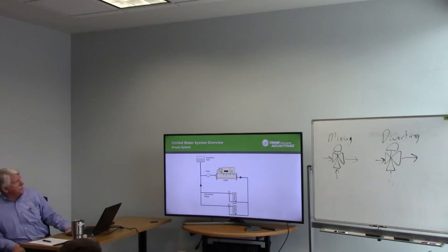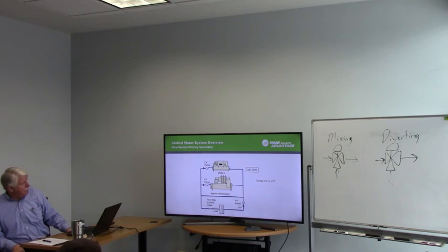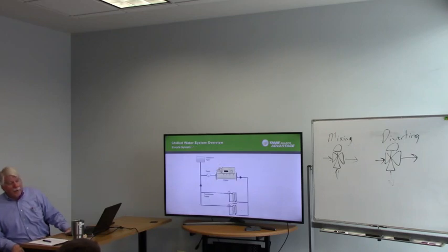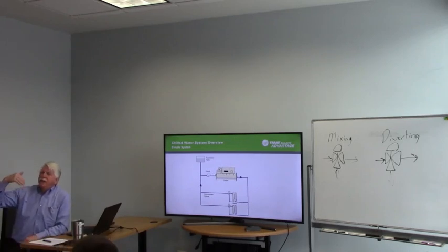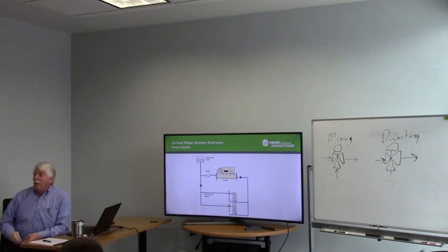So this is a simple system. Hey Tony, how much energy do you actually save when you're varying a VFD? Is there a calculation, like 10% on a VFD saves X amount or something like that? If you are talking about a given system, in other words, so many GPM and so many feet of head, and you can change the speed of it, there's a thing called the fan law, which applies to pumping systems, okay?